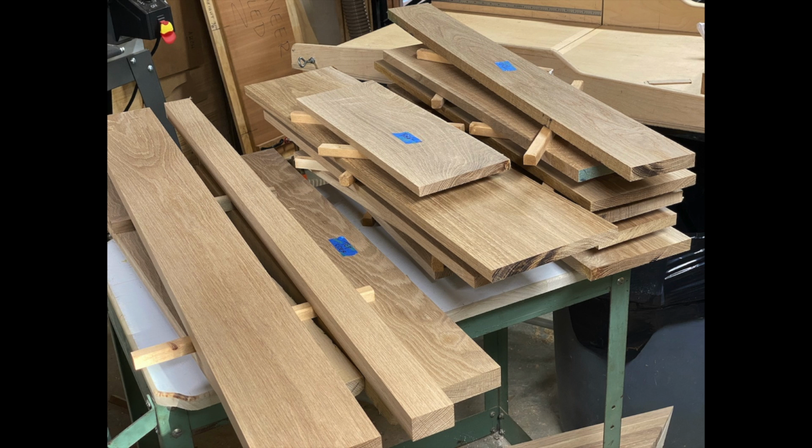Then when I start the project, I mill to a larger rough dimension, usually 1/8 to 1/4 inch for width and thickness, and 1/2 inch or more for length, and store it in my shop with wooden stickers between them. In this way, I know it has reached EMC in my shop. Then as I work on individual components, I mill them to final dimension, do the joinery, and assemble them within a day or at most a few days. This minimizes many of the problems discussed so far.